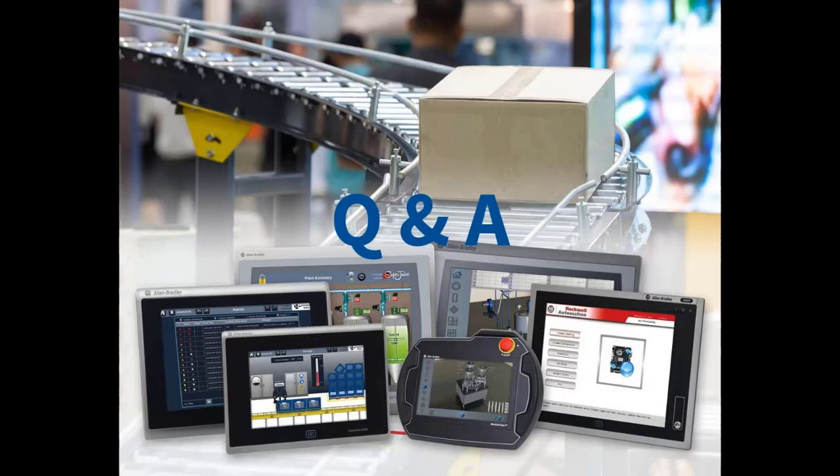Is the Series B programming USB port inactive like Series A? It has the same functionality as the Series A. There were some workarounds in the Series A where you could load a USB driver on your computer, depending on which operating system you were running. So you could set up a default IP address and download through the USB port at that default IP address. But I know for sure it doesn't work on Windows 10 or the newer operating systems. It worked back in the XP days, and it worked with Windows 7 and 8. So I believe the Series B will function the same way.